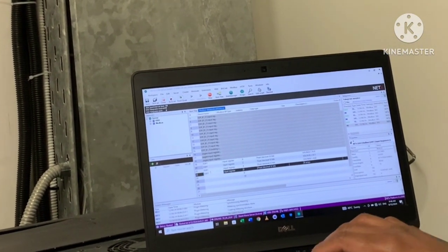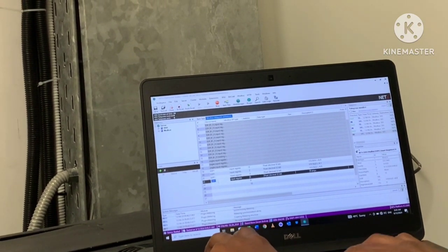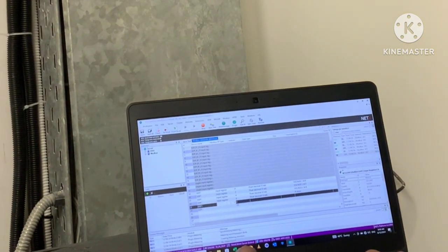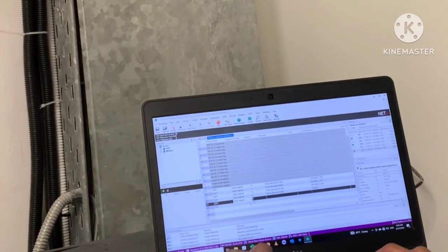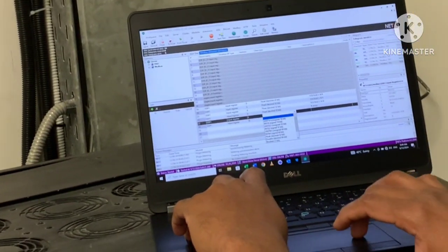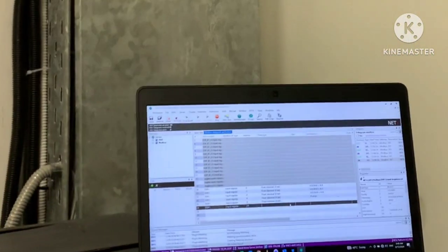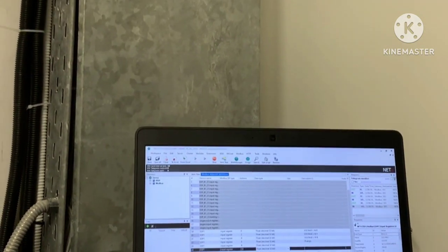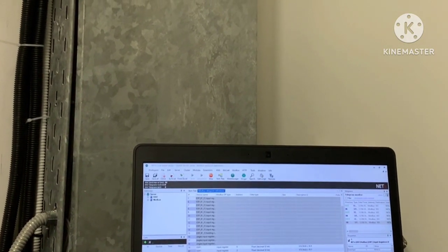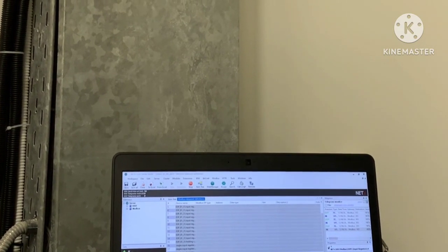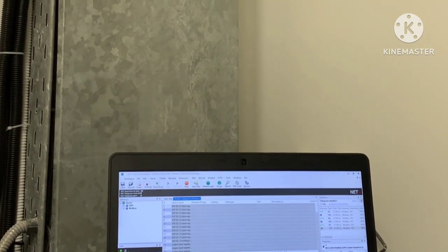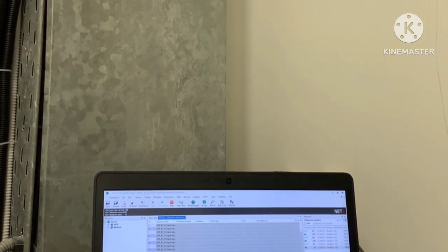So, and the rest of the things are the same. So I will just copy and paste, so you will get the data from here. So all the things are the same, input register. Okay, just go to input register, and the float value, all are float value 32 bits. Okay, so just go 32 bits from here also, and from here also you have to go 32 bits, and name. The rest of the two are for the amperes, but in different phases. The second one is for Y phase, okay, and the last one is for B phase.